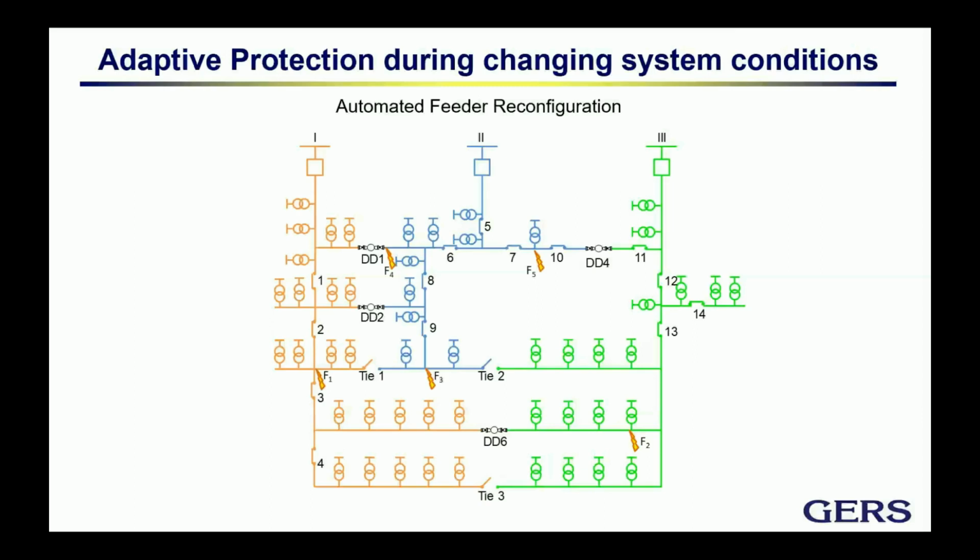Let's suppose that we have the fault F1. So, question, if we have that fault, the breaker here at substation 1 trips the whole feeder. That is step number one. The second one is to isolate the fault. So how do we isolate the fault? So we open switches 2 and 3. So the faulty section remains only associated to these 4 distribution transformers that I am pointing with my arrow.